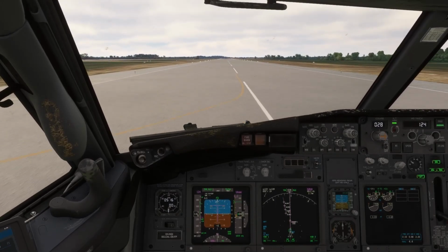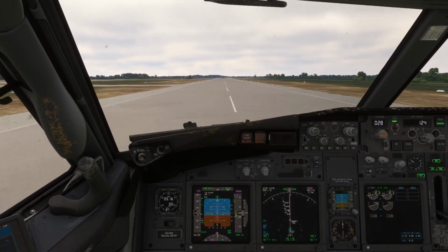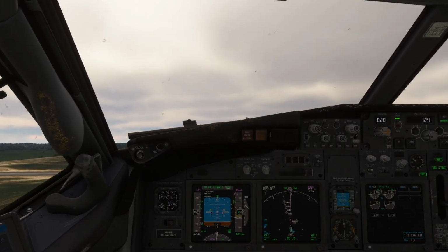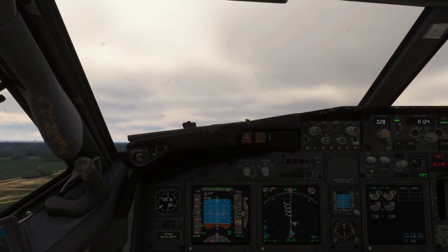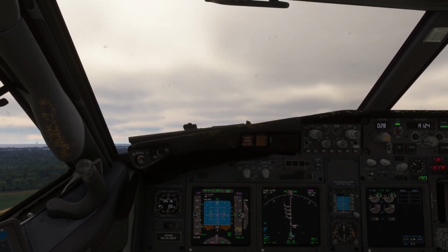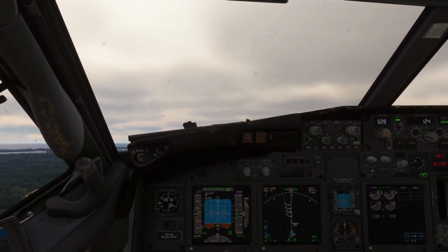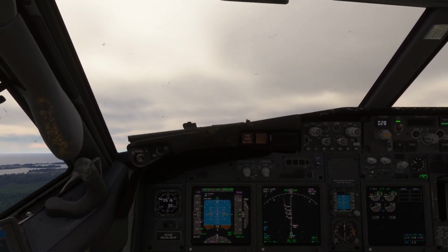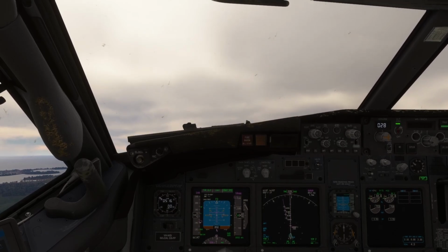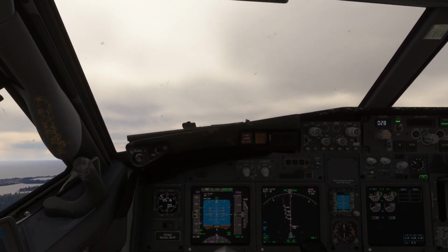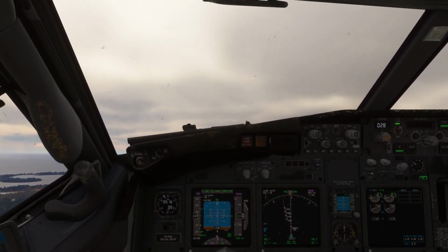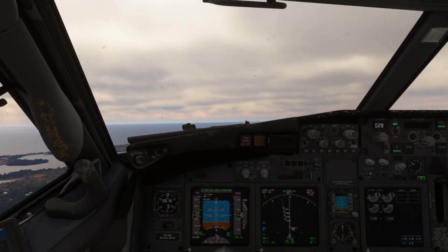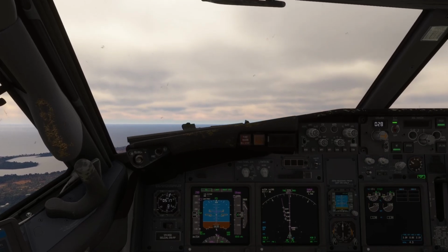On the 320, the fly-by-wire is different. You've got the 1G flight path philosophy. You can hear the PTU going off. All these sorts of things are simulated faithfully. And unless there's a bug, everything works just like it should in the real plane. You've got an autopilot flight director system that gives you accurate guidance in both pitch and roll channels. You've got to add in custom waypoints in the FMC program, approaches, offsets, all these things.